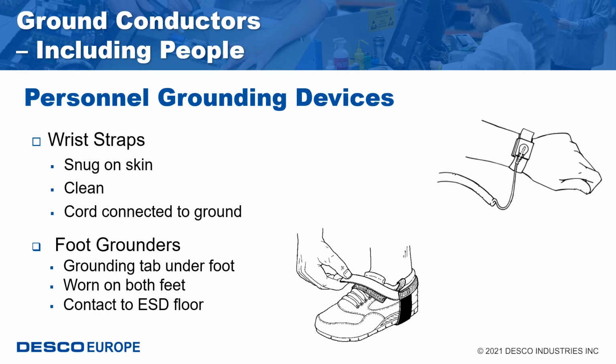Personnel grounding devices directly connect an operator to ground, removing static charges from the operator's body. A basic principle of ESD control is to ground conductors, including people, at ESD protected workstations. Wrist straps are the most common grounding device used in the industry to ground people, who are the most significant cause of ESD damage. The wrist strap will safely and effectively remove static charges from your body. A wrist strap must be properly grounded to a wrist strap ground.